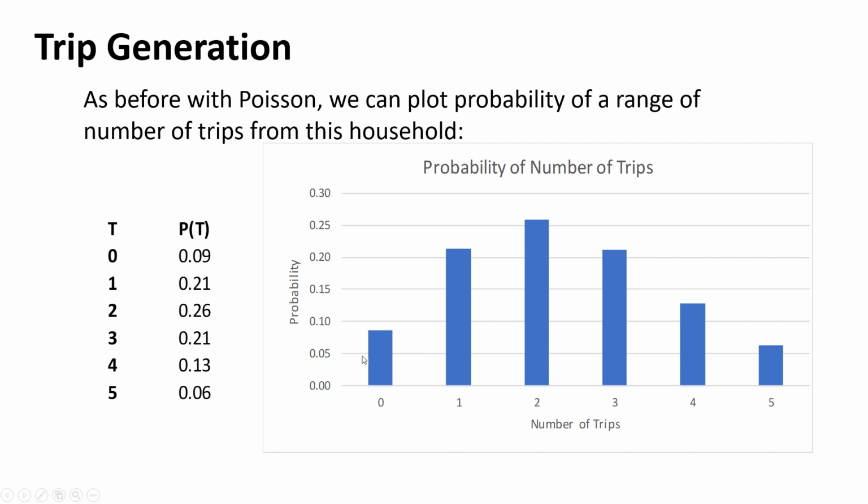So that gives you a bit of a sensitivity analysis for your trip generation, and you can get that through this model, setting it up this way. That's another use. But again, it's just an alternative way to calculate trip generation. Those are the two that we talk about in the book. I'm sure there are others in the research, but these are the two more common ones we use. Least squares is the most common. The Poisson is a newer one and is not used as much, but it's an option, and it gives you slightly different information.